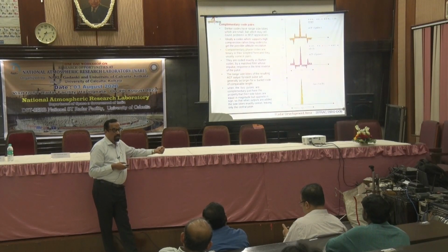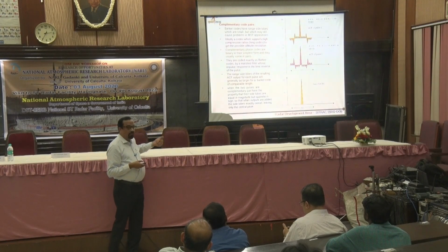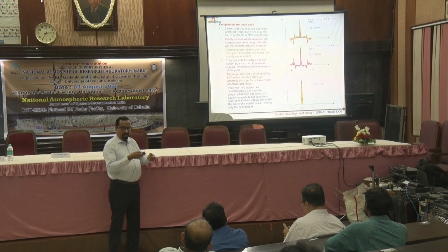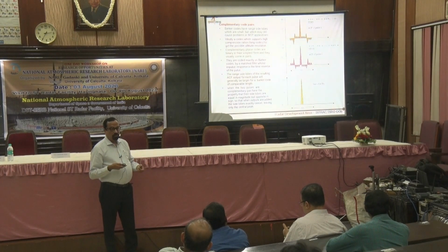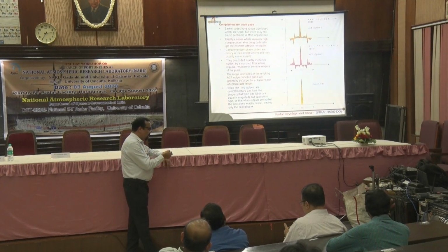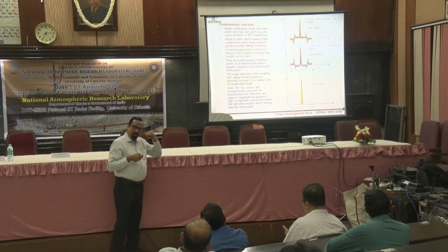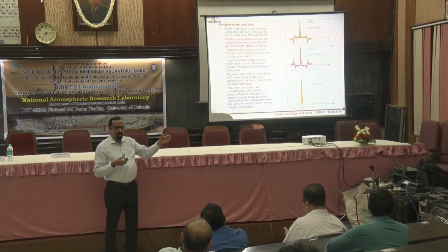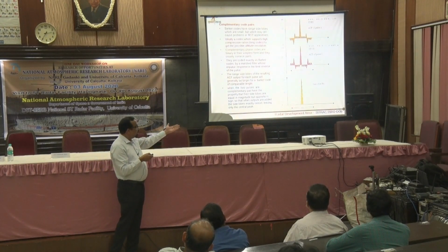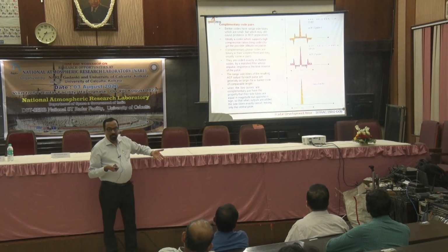You see, in atmospheric radars of this kind, we need a very low signal to be boosted back. So we use such techniques, and at the same time the leakage to the adjacent range gate should be as low as possible. So you sum these two things up. Instead of getting so many small sidelobes around it, I am getting a single pulse. Two streams of pulses go one after the other. Take those two streams back, decode them, add them together, and you get the desired result. This is what we do.